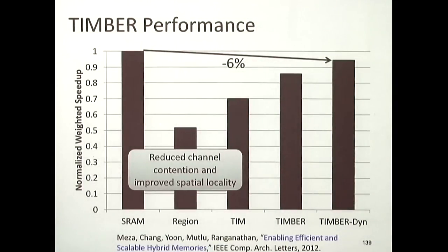OK. Just to give you some results of this, basically, this is the SRAM tag store. If you have an SRAM tag store, that's a lot of overhead in the memory controller. If you actually put the tags in DRAM, but not in the same row as the data, you actually lose performance significantly. Basically, here you're doing 2 DRAM accesses to get a DRAM cache hit, but they're not in the same row. The tags are in some part of DRAM that's separate from the data. Basically, your performance degradation is huge compared to an SRAM tag store. That's why this is an important topic.